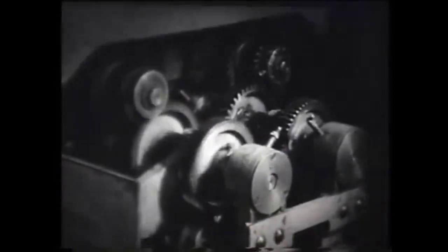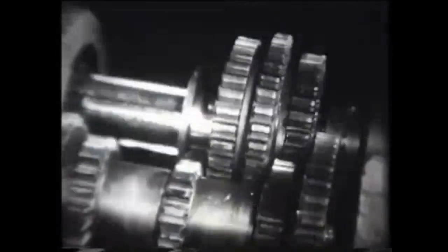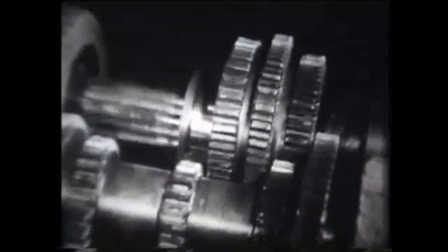What are they for? They are necessary to change the speeds and directions of movement of the actuators of machines, to set several mechanisms in motion from one engine, and to provide a greater torque of the executive body than the motor shaft. And in those cases when the working bodies of the machine perform a different kind of movement than the engine shaft.